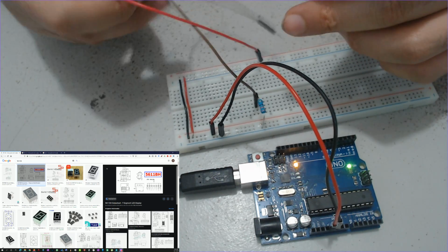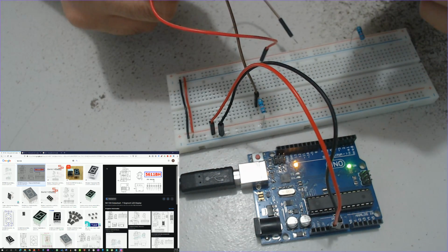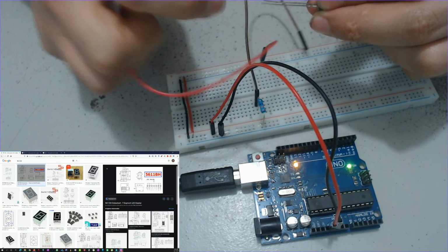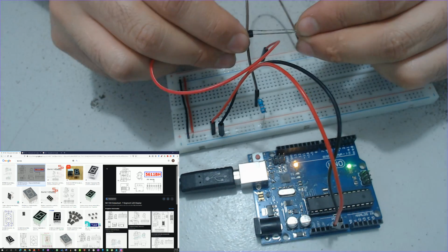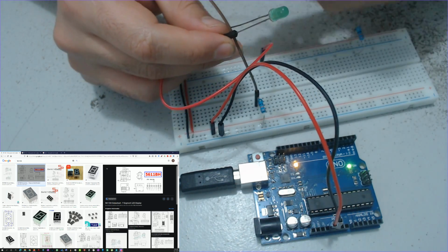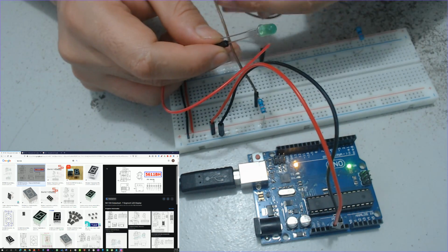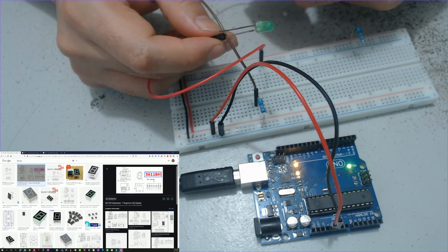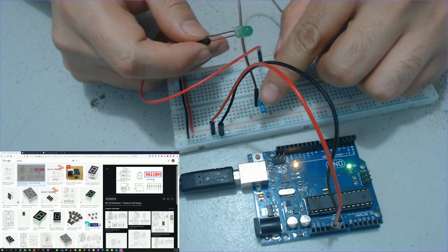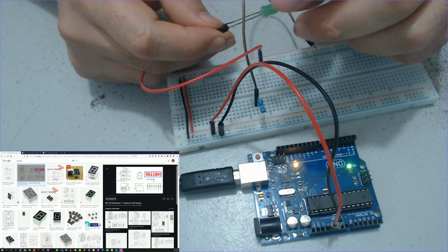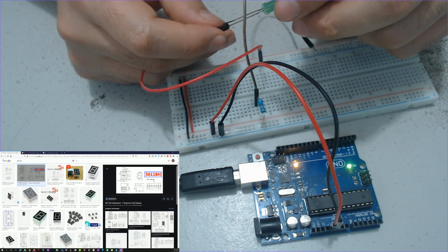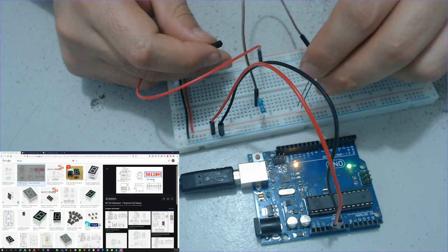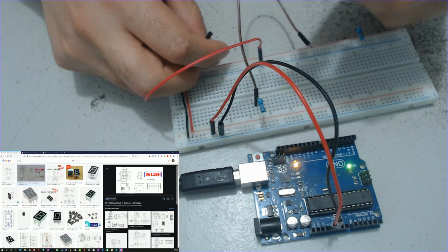I put the positive connector to the long leg of my LED. This is the long one. Here it is. And then when I provide negative connection, it turns on. That's it. Remember, I use this resistance to limit the current in this element in order to prevent any damage. If I put this directly in the breadboard like this, I may damage it, and I don't want to.